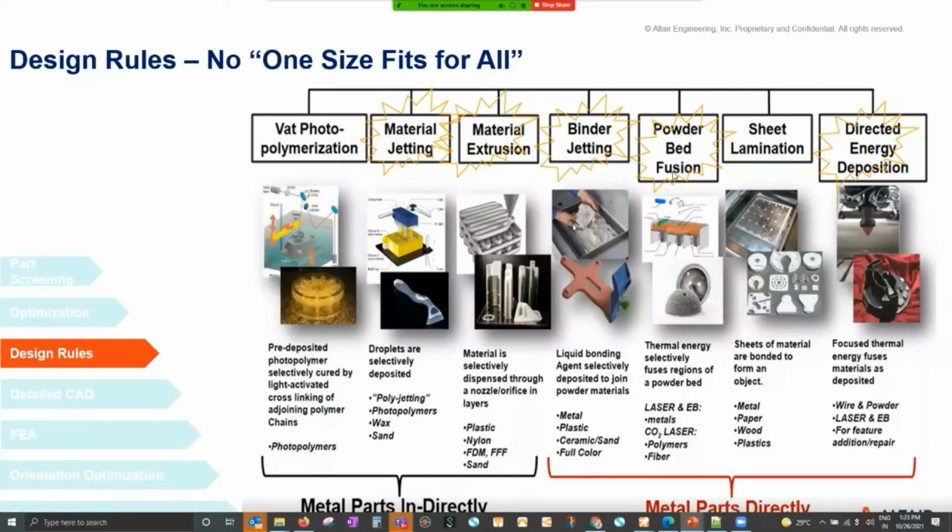powder bed fusion, that is LPBF, it has a different rule than, say, binder jetting. The reason being that binder jetting has additional steps, or rather many different steps, where you start with binder, then you go to an oven where you cure it, and during that process there is a change of mass properties of the component, which can make it prone to fall and break. So those are different requirements it has, right?